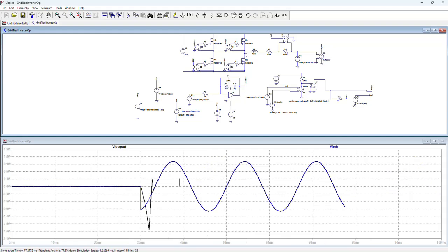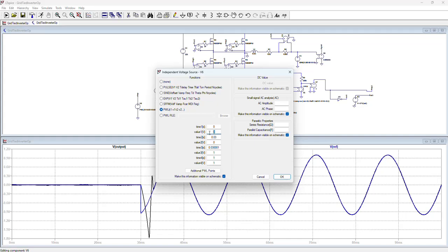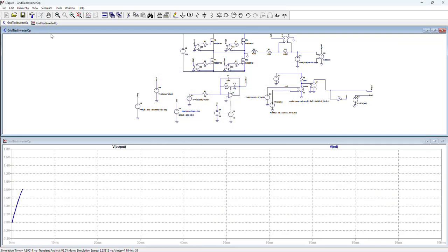Again, instead of applying the full nominal current, we can apply a ramp, which will gradually increase the amplitude of the reference, and this transitory behavior, of course, will disappear. Let's return here to from 1 to 0.5, and let's emulate again just to check if everything is okay.